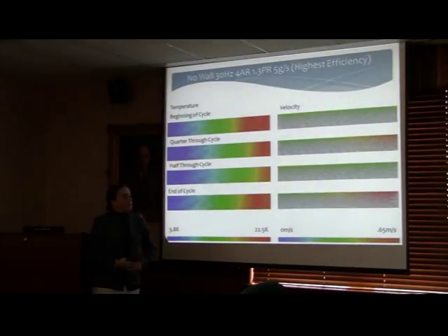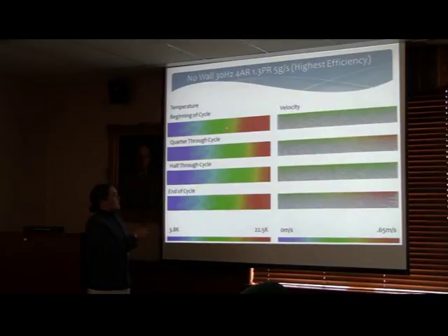Alright, so this is what Fluent produces as far as imagery is concerned. This shows stage 1 of the pulse tube cryocooler, where the piston's pushing down, the mass flow hasn't really happened yet, and the velocity is sitting in the middle. Then you get a higher push this way, you get that expansion of the cold, and as the piston moves back up, you get velocity flowing back the other direction, and your cold is going to expand even more so that it can accept the cooling load. Then it's going to heat back up from that cooling load, and the mass flow rate is going to push the piston back to the other side.